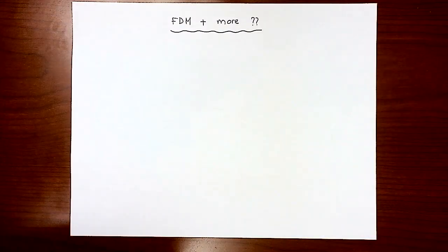In this video, I would like to build on the one-dimension heat conduction problem that we used in multiple recordings, looking at how to apply the backward finite difference method. Then we used the central finite difference method, and then we explained how to use different iterative techniques or schemes like Jacobi and Gauss-Seidel to solve the system of linear equations.